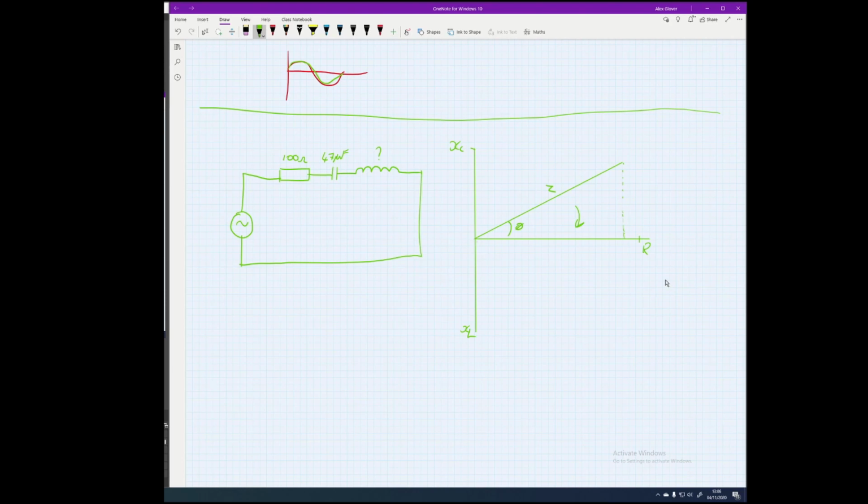And the only way to do this is to create another phasor here, which is a mirror image of the one on top, which should allow it to rotate it back this way. So we end with just a line across here with just the resistive element and current and voltage lining up, and we've got a complete power factor correction.